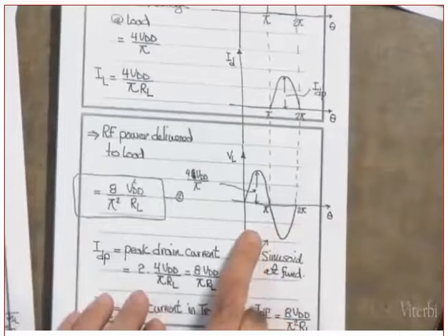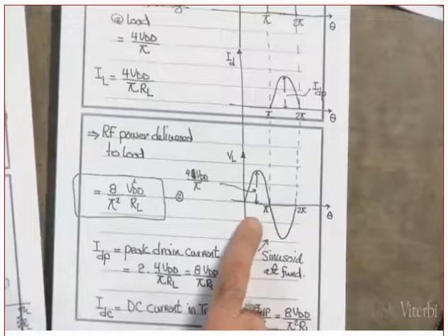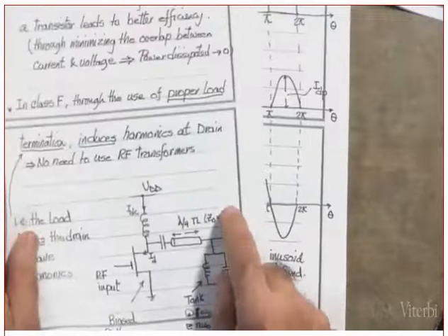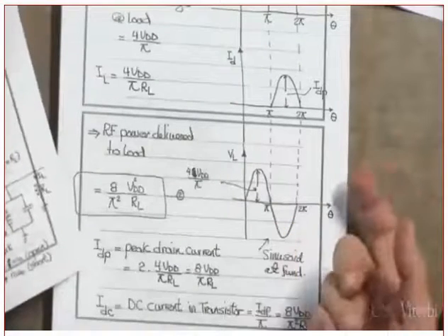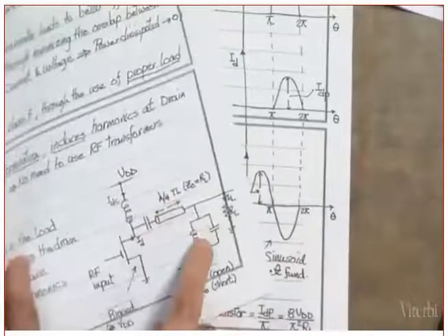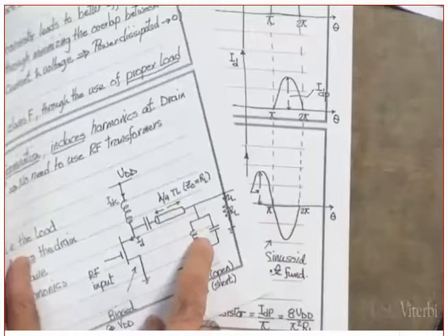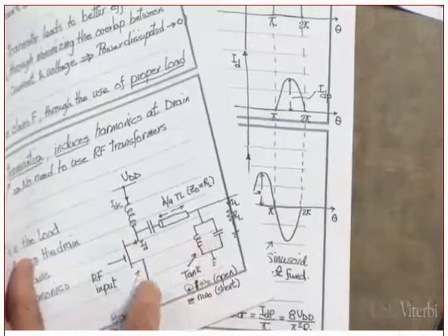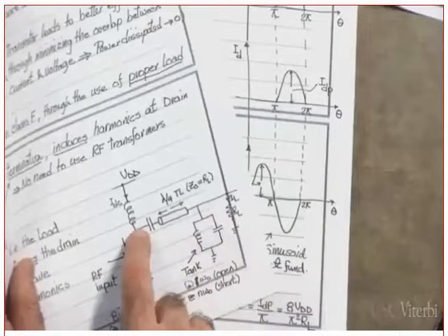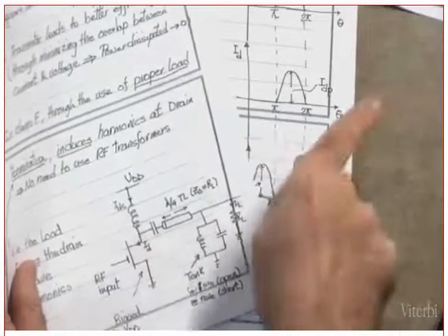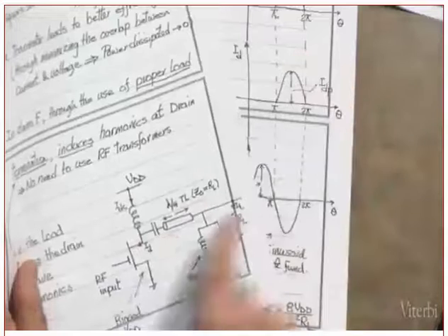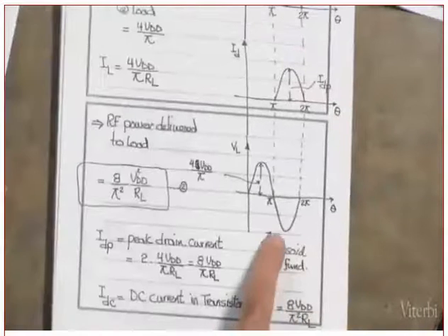Okay. Now, what is this all about? Can you explain to me where is this? That is the voltage across the load. Yes? Why is it a sinusoid? The even harmonics are going to ground, and the odd harmonics remain in here. Yes? So the only one that goes in there is the fundamental, goes through the capacitor, which is this one.